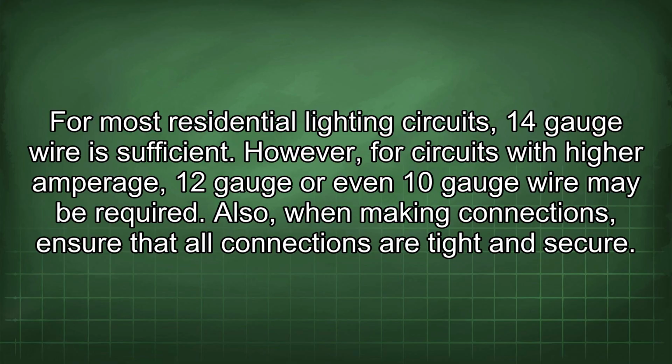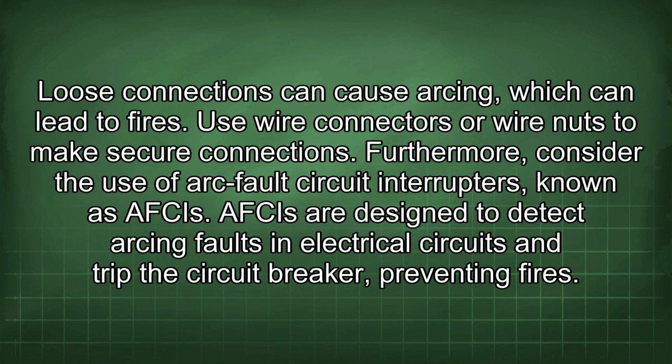Also, when making connections, ensure that all connections are tight and secure. Loose connections can cause arcing, which can lead to fires. Use wire connectors or wire nuts to make secure connections.